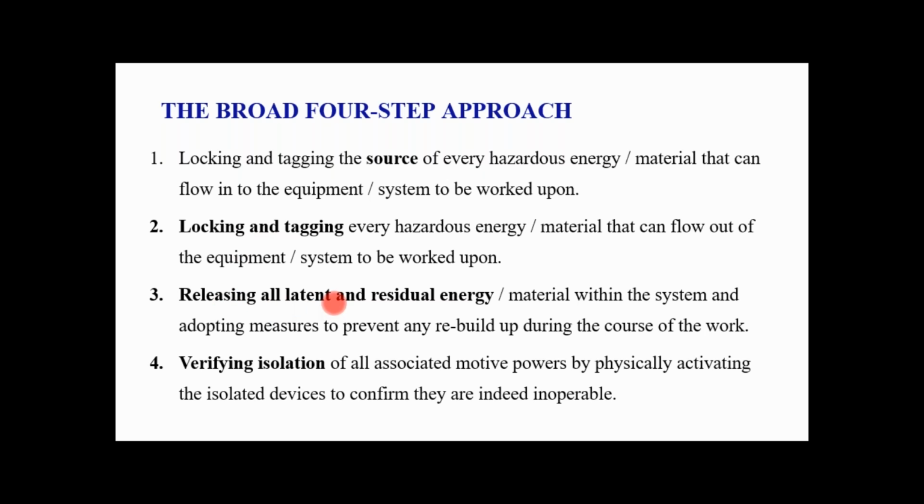The third step is releasing all latent and residual energy or material within the systems and adopting measures to prevent any rebuild up during the course of work. So we have to release all the latent and residual energy. When we talk about thermal energy, latent heat can be trapped or remain in that system itself. So we have to remove or eliminate this latent heat.